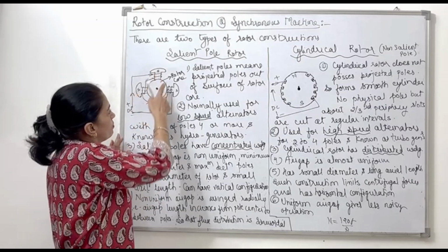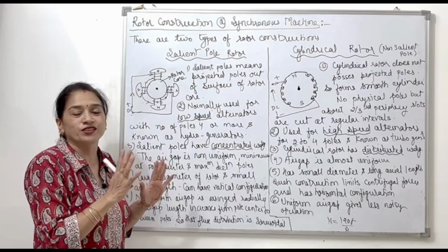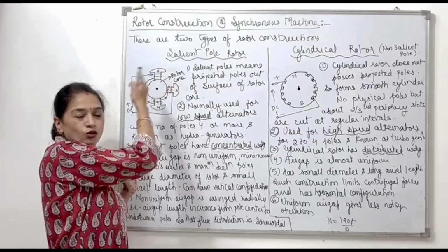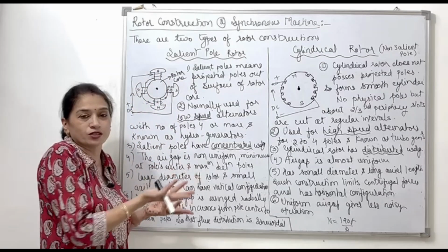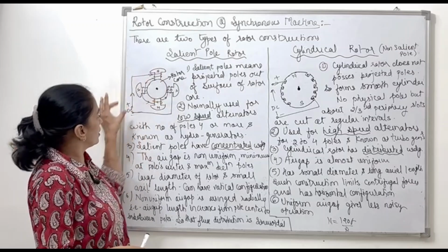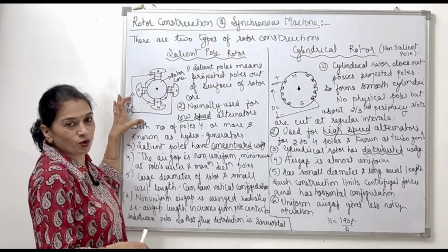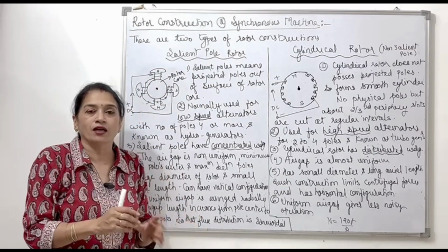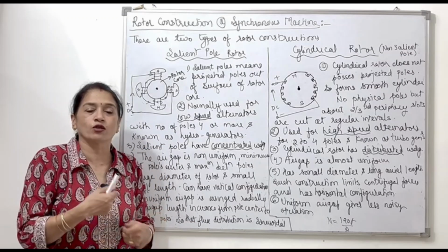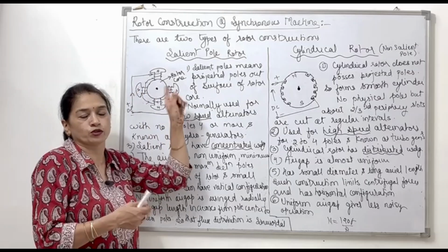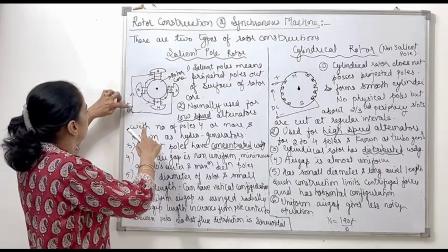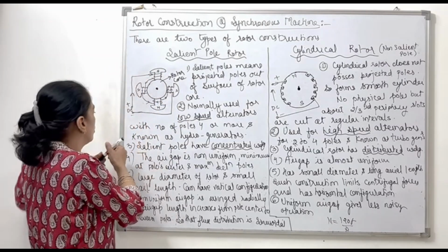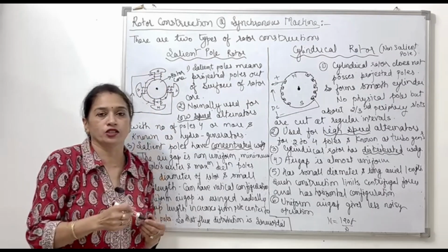Now, as I said, I am wrapping the winding over here. This is nothing but a concentrated type of winding, because we have the turns placed together over the same position. So this is the concentrated one. DC field excitation is given through this plus minus polarity, some DC voltage is there, and all these windings are in series and wrapped in such a manner that north pole, south pole, north pole, south pole are generated. This is the positive polarity, the current flows like this, and again we have the negative polarity of the wire over here. This way this particular connection is made.